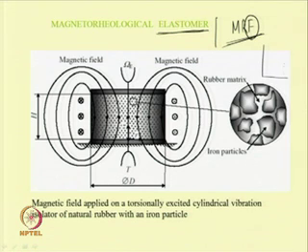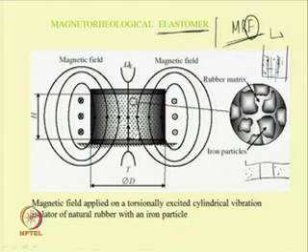In case of magnetorheological fluid, the iron particles are embedded in the fluid and then one applies a magnetic field to align the iron particles, and in that case it will act as a damper. Also nowadays some researchers are using magnetorheological fluid inside the sandwich structure. In between the viscoelastic layers one may use magnetorheological fluid also.